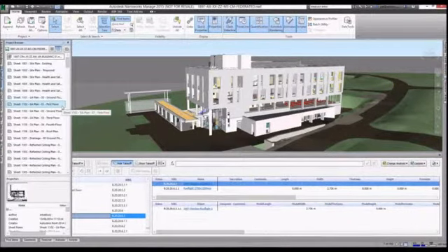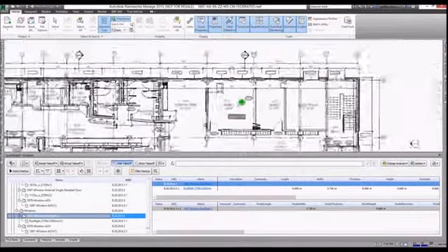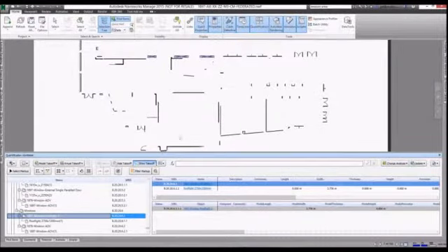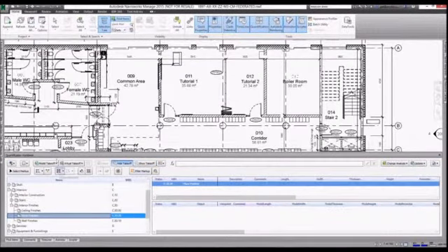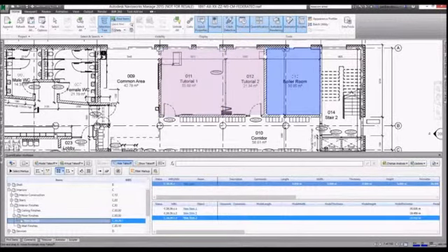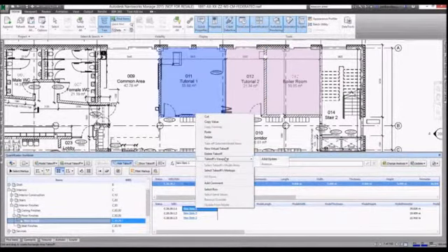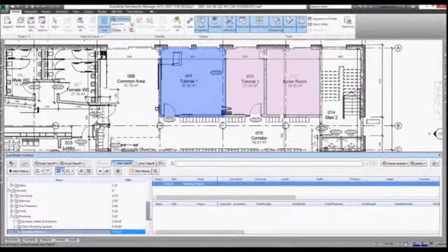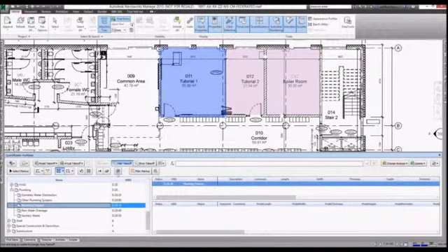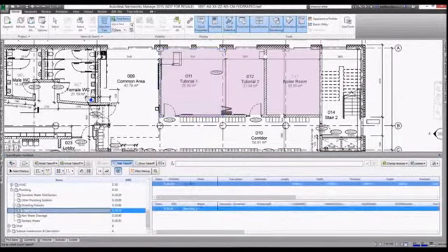As in 3D, in any 2D sheet view, it is possible to isolate or highlight items already measured. Tools such as the Area Takeoff tool will allow takeoff of finishes where these have not been specifically modeled, and these areas will be added to the workbook. Also, individual items can be taken off by tagging these in the sheet view.